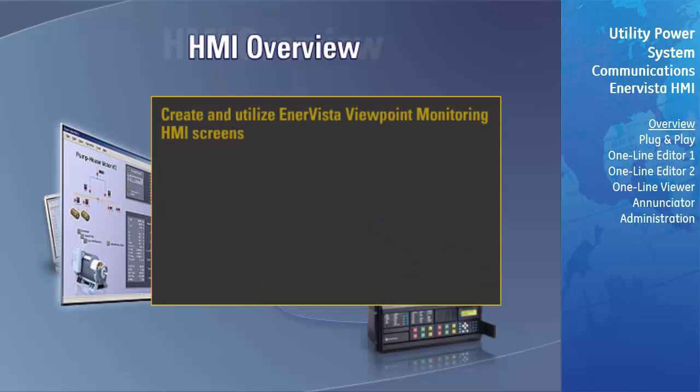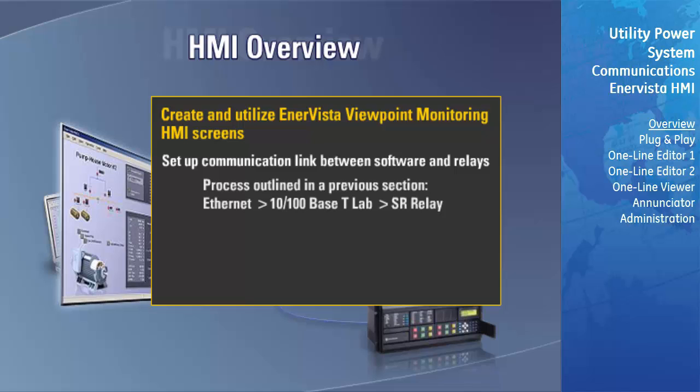The procedure to create and utilize EnerVista Viewpoint Monitoring HMI screens can be broken down into the following steps. After launching the EnerVista Viewpoint Monitoring software, we would first set up a communication link between the software and the relay or relays. We already outlined this process in a previous section. If you would like to review these steps, please click on the Ethernet button in the top menu. Then click on the 10/100 Base T Lab button on the left of the screen, and then launch the movie titled SR Relay. We'll cover the remainder of the steps in this section of the training CD.